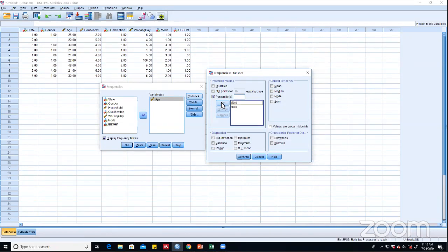For example, when we are talking about speed modeling, initially you plot the cumulative graph of the speed profile, that bell shape or normal distribution we used to plot. And we used to consider four kinds of speed limits: the 15th percentile, 50th, 85th and the 98th percentile. With respect to the average, design and upper limit, we used to define them.